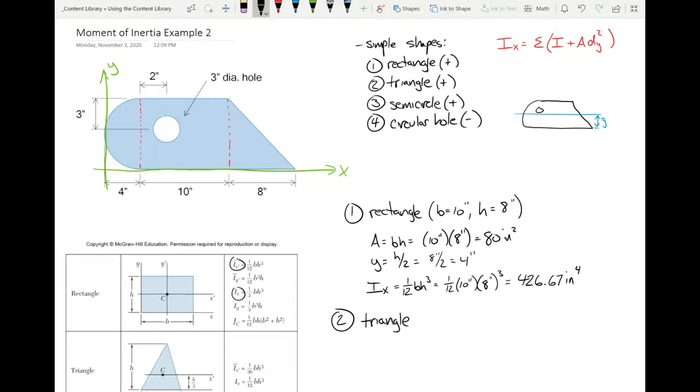All right, so the question was, where is the height, 3 inches or the 8 inches? What we're talking about here is sort of a dimensional thing. If you look at the rectangle, right here next to that rectangle is a semicircle. And that semicircle has a radius of 4 inches. So what is this dimension? It's 2 times the radius. That's where we got the height of the rectangle to be 8 inches.